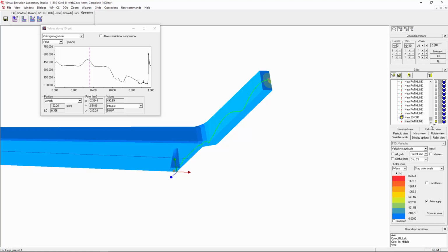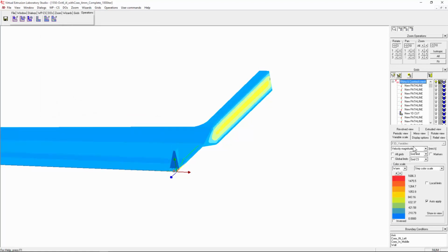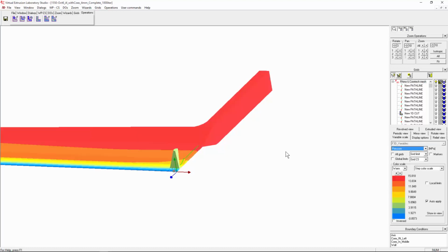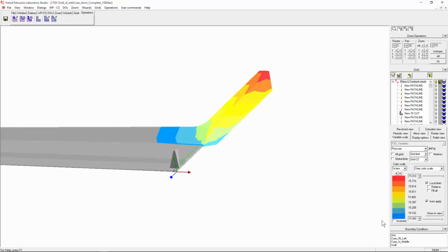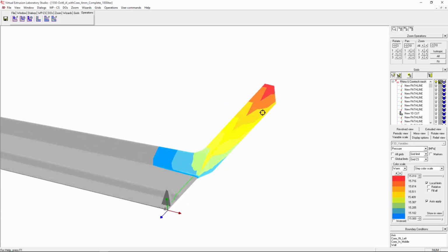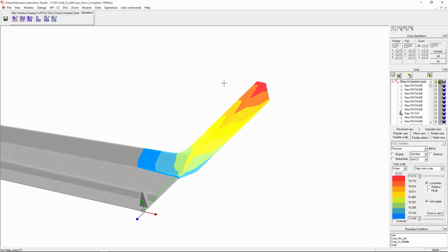We may also see that when we look at the pressure on the main grid, because when you do a pressure and you use local limits, you put here, say, 15, we'll see that something is really happening here in this channel, because we would expect isobars to be perpendicular to the channel here in this position. So something's really wrong.